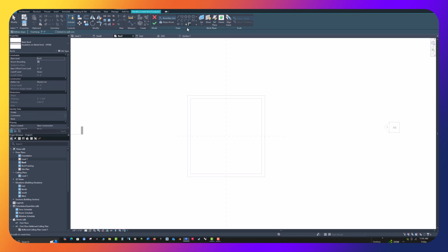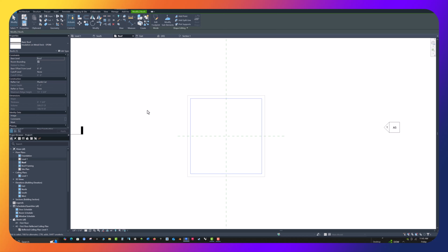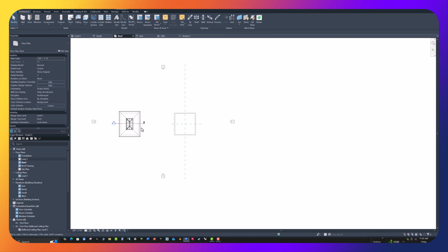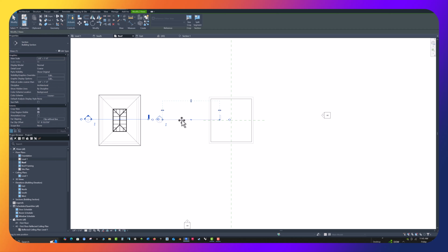And I'm going to, I don't want any slope, so I'm going to turn off define slope and pick my walls tool. Here, I'm on the inside here, here, and here, and I'll say OK to that. And let's move this section over here.